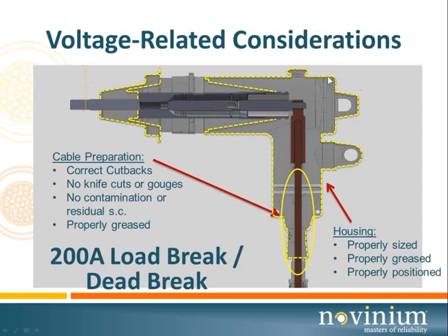When we slide the housing on, we want to make sure it's positioned properly. By proper, we want to make sure that the lug is fully up to the top here. When that's fully up to the top, it allows the connection to be made to the probe. Now, if the housing is not properly positioned, you're not going to be able to get the probe in. But you want to also make sure that those probes, the threads, are aligned straight out so we don't do any cross-threading.